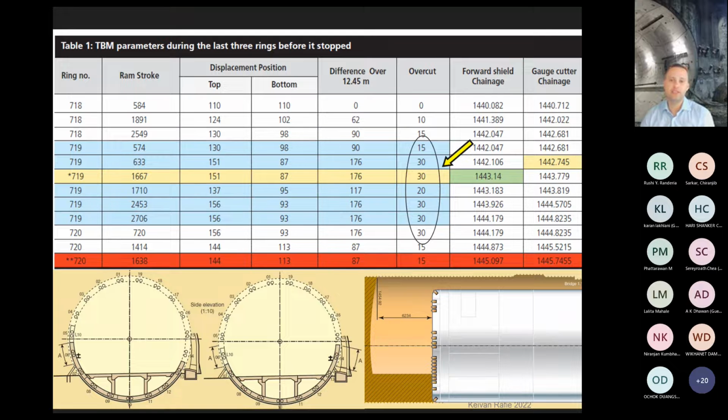So the chain of events that led to the TBM jam occurred around ring 719. The TBM entered the smaller sub-tunnel profile and was close to its final position for relaunch. The survey revealed that the TBM was slightly higher than the designed tunnel alignment, and the TBM operator was asked to center the TBM before the cutter head stopped for relaunch preparation, so we could start exactly where we needed.